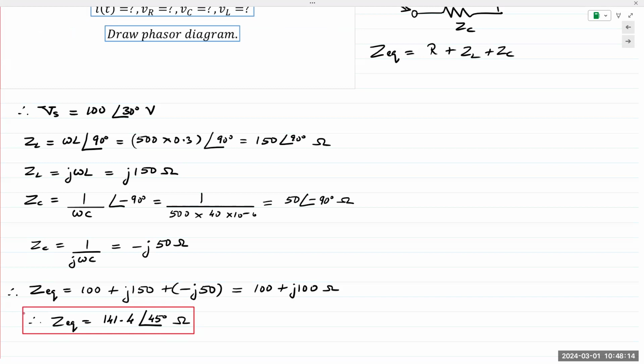Now, think back to chapter 2. You have three resistors in series, you're applying a voltage, and you wish to find the voltage across each one of those three components. We can find the current. What happens to voltage across a series connection of resistors? It drops, but it's divided. You could also apply voltage division. So if you don't wish to find the current, you can apply voltage division directly, which I will write up the equations for here. I would encourage students to practice on your own calculators outside of class time. But let's first take it step by step.